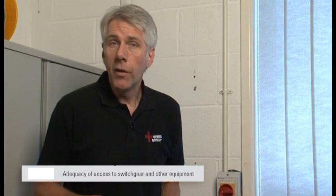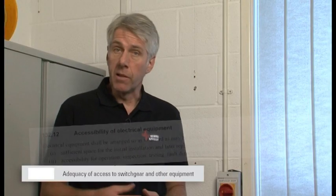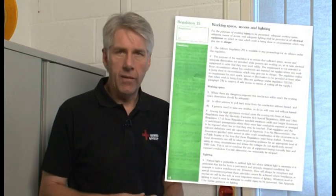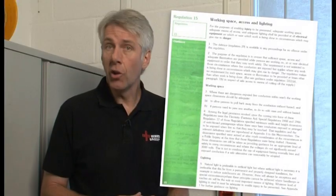The next item is adequacy of access to switchgear and other equipment. This is referring to the access required for future maintenance and similar activities, including periodic inspection reporting, and is a requirement of Regulation 132.12. But a good source of information on adequacy of access is provided in the Memorandum of Guidance for the Electricity at Work regulations, which also lists sufficient lighting as a requirement.